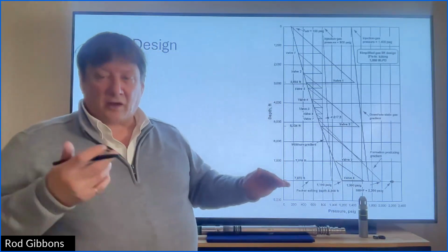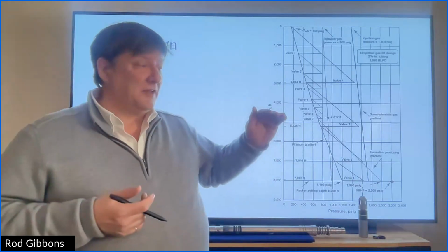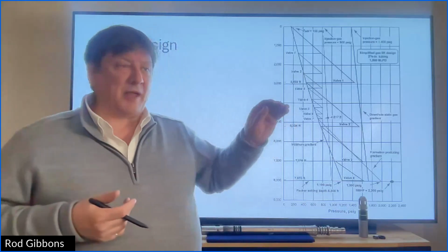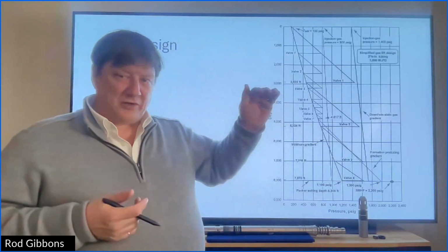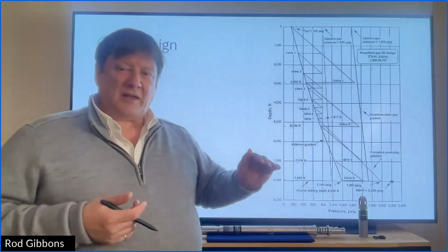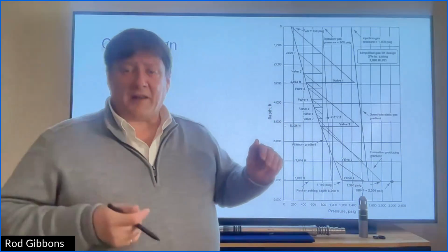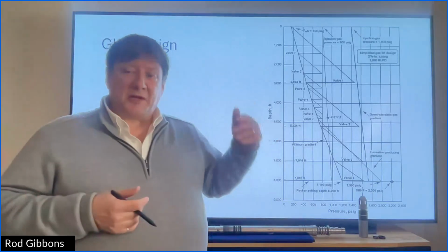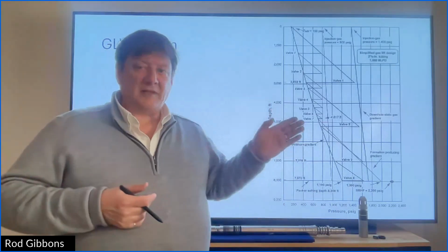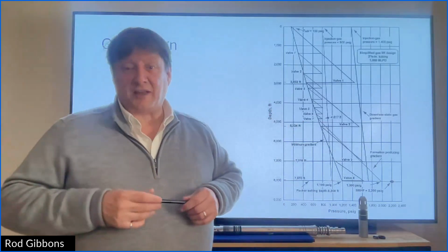Those are unloading valves, and they have a nitrogen charged bellows in them to close them once you get the fluid level down. Then you get down to your operating valve, which is where you're going to be putting your gas lift in as deep as possible based on the surface pressure you have on your gas injection.